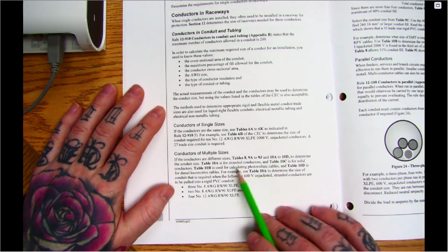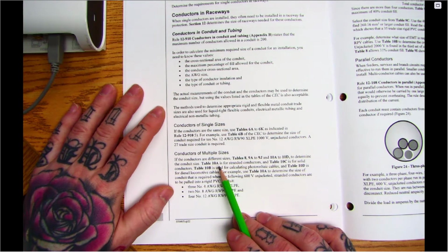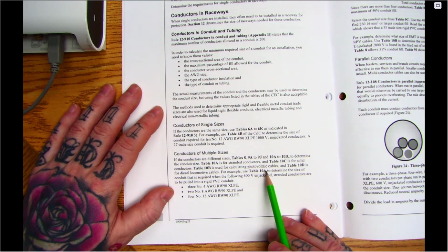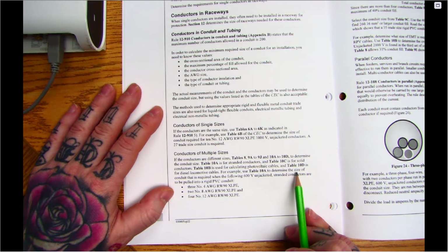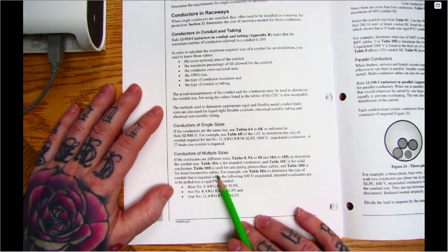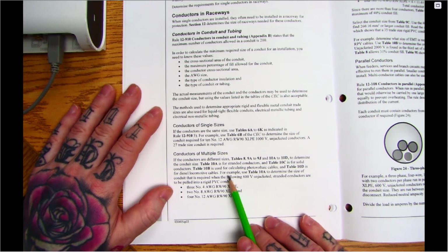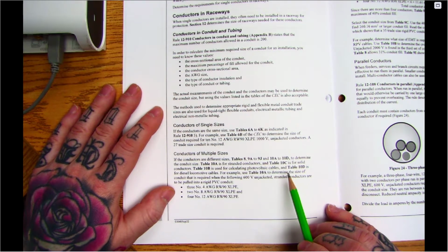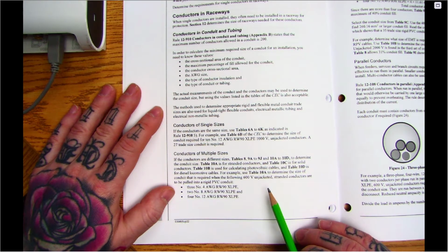Now, things that are important here, we'll get used to these by going into them quite a bit, but 10A is for stranded, 10C is for solid, and B is for photovoltaic cables. And Table D is for diesel locomotive cable, so it's a DLO on the table. So if you get a question asking about DLO cable, that's Table 10D. I do get asked a lot of these questions, and they are right in the module, so make sure you have a read through, because we do have questions like this in our bank too.